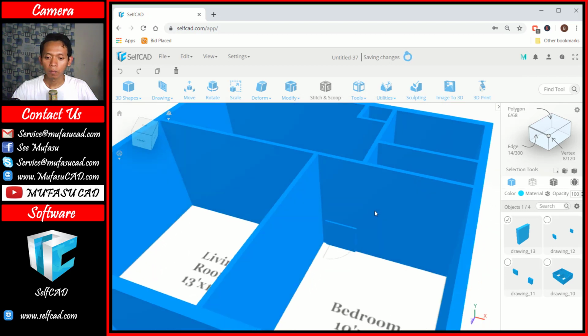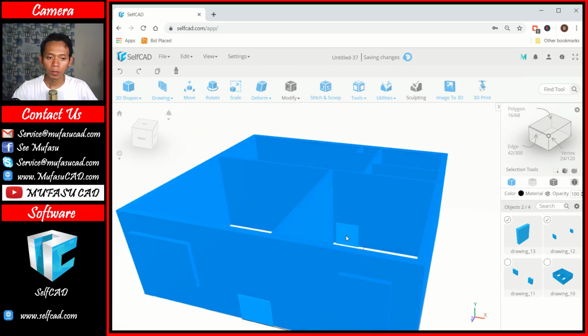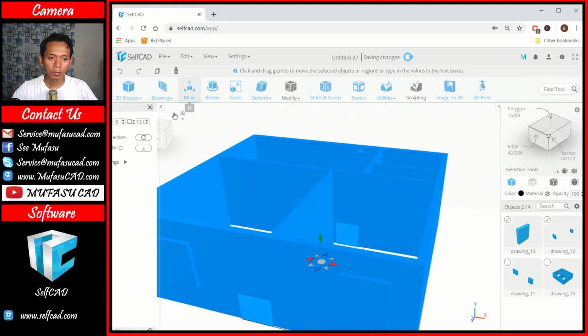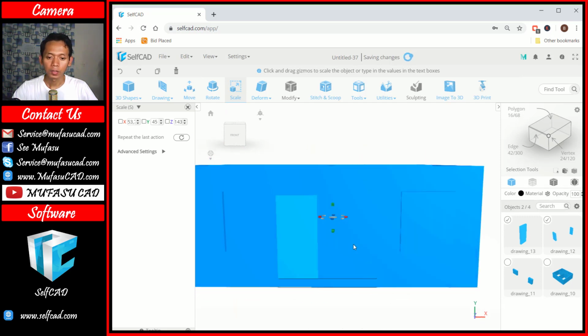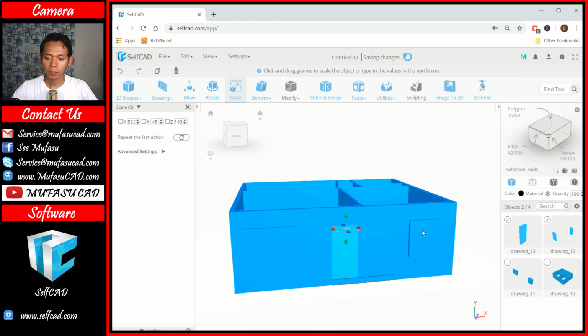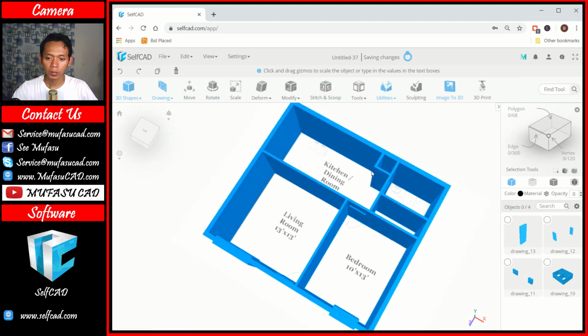Now we will set this door dimension. Okay, you can select these two objects, and next we can move this object in the y-axis by 5 points. And I will use the scale command to scale this model in the green axis. You can move into here. Okay, this is for the door and this is for windows. Next we can use the cut command to cut this wall.